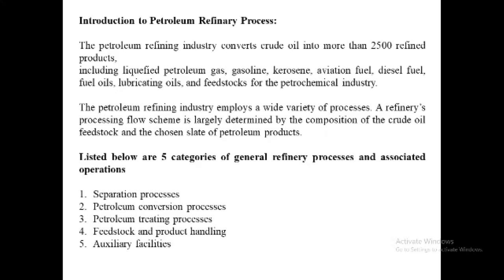After that, the petroleum treating process stabilizes the upgraded petroleum products by separating them from less desirable products and by removing the objectionable elements. Undesirable elements such as sulfur, nitrogen, and oxygen are removed by hydrodesulfurization and hydrotreating, chemical sweetening, and acid gas removal. Desalting is used to remove the salt, minerals, grit, and water from the crude oil feedstock before refining. Asphalt blowing is used for polymerizing and stabilizing asphalt to improve its weathering characteristics.